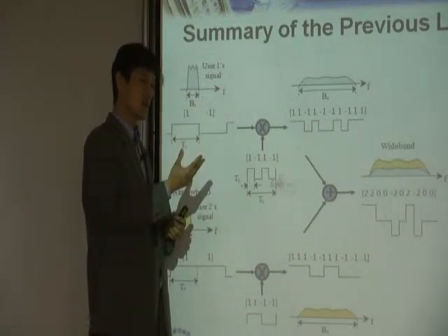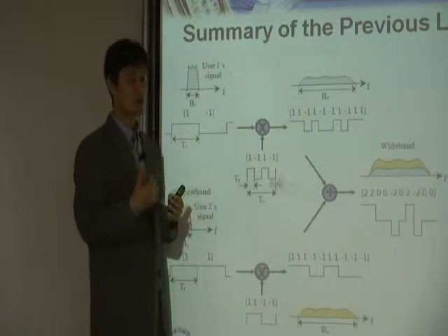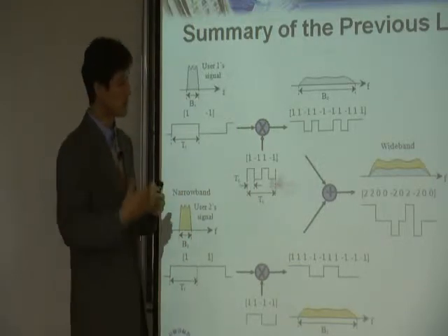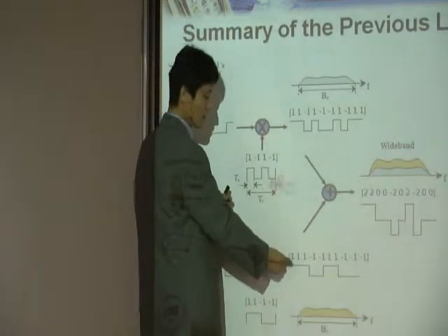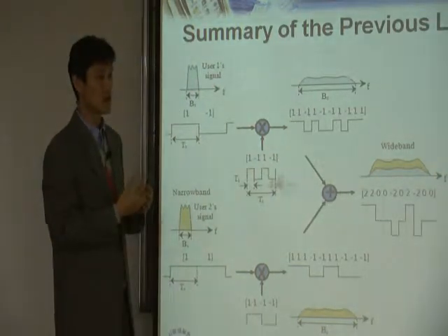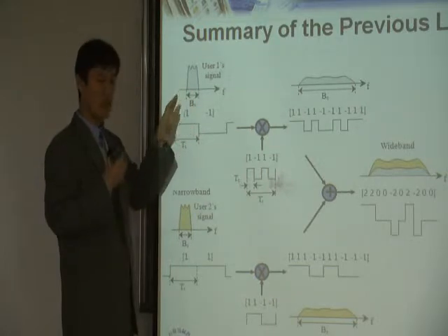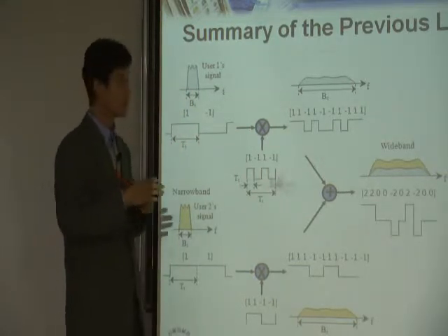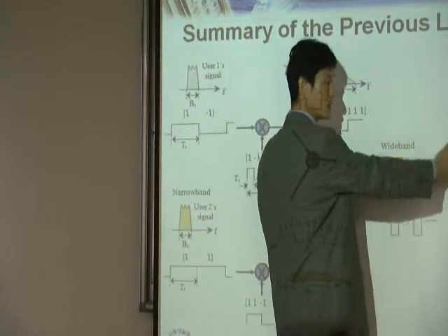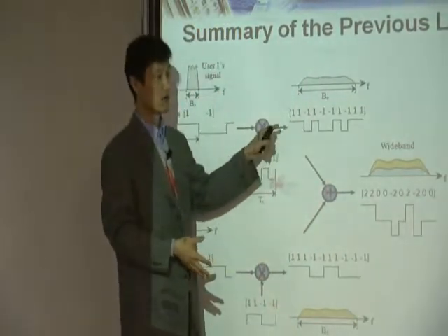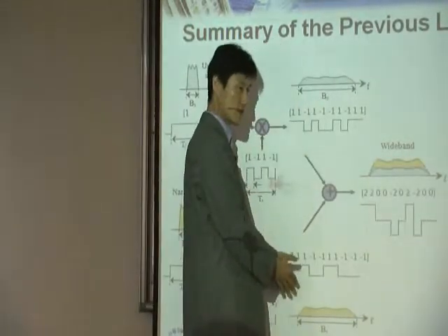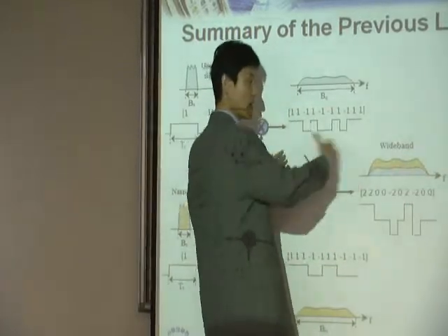And when you search the base station, what that means is that you are doing synchronization. There is a certain time synchronization process. By going through that process, somehow your symbol duration and symbol boundary is synchronized. So ideally speaking, when you wake up, you anyway have to do the synchronization process. Therefore, ideally, your chip boundary is exactly synchronized with the base station's boundary. Same thing for others, right? So this guy synchronized its own time with the base station. This guy also synchronized its own time with that base station. So everyone does that.